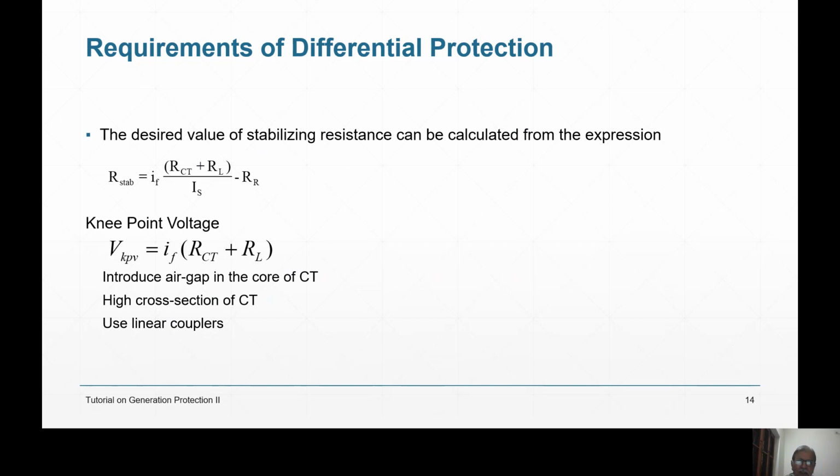Within the hollow, distilled water is flowing and it is very nicely designed. So the possibility of a double line or triple line fault may occur, if at all, in the overhung portion. Otherwise, if differential protection operates, people will doubt something else. And that I have discussed in one of the seminars, one of the webinars.